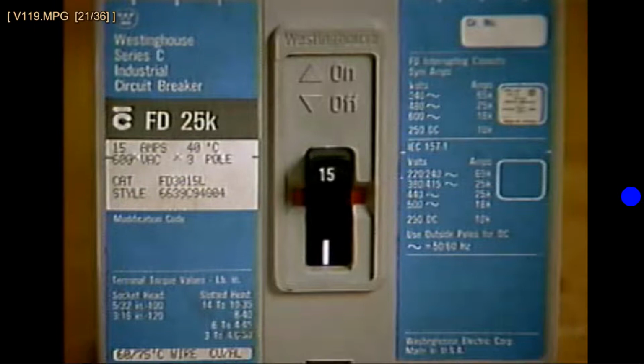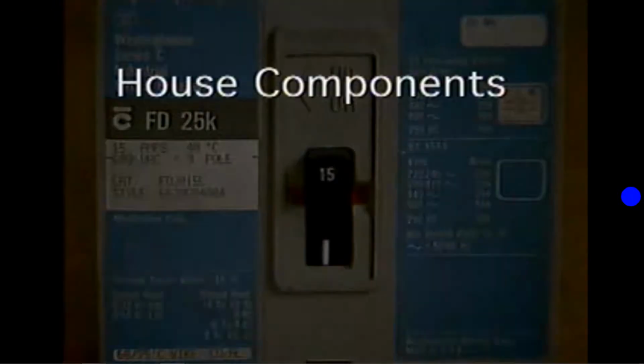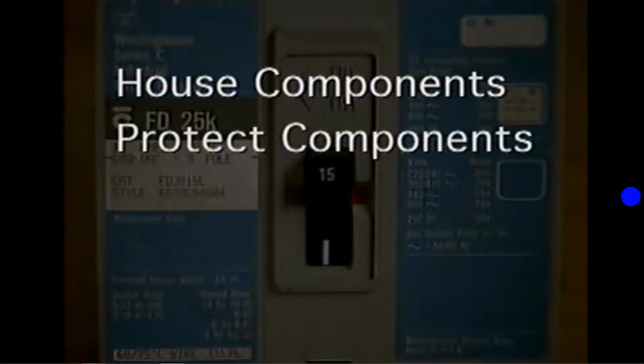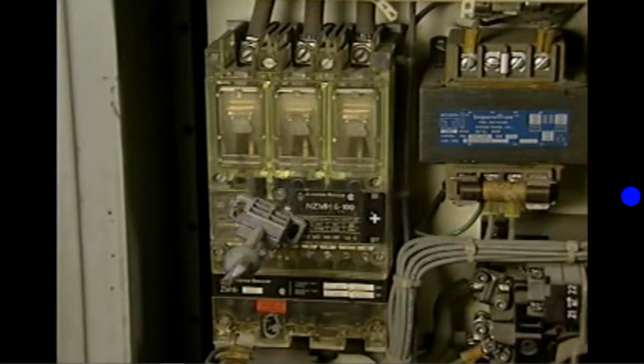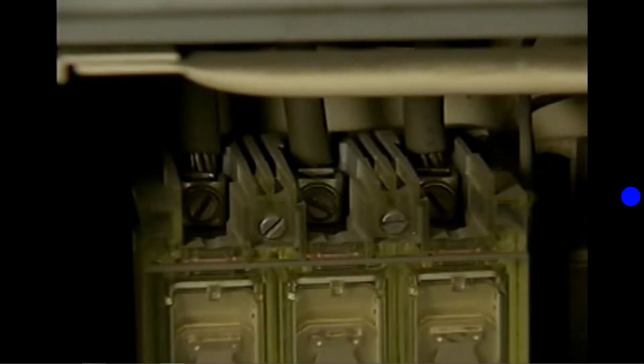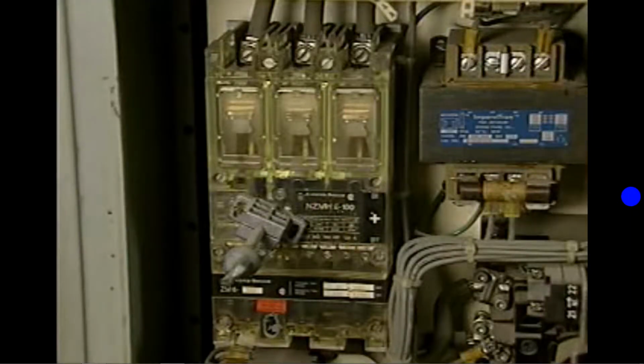The casing of a molded case circuit breaker has three primary functions: to house the breaker's components, to protect the functional components from contamination and damage, and to prevent personnel from touching energized components in the breaker. Molded case circuit breakers require relatively little in the way of maintenance. Essentially, the only maintenance that is required is to make sure that the conductor connections are tight and free of corrosion, and that the breaker is kept dry and free of accumulated dust and dirt.